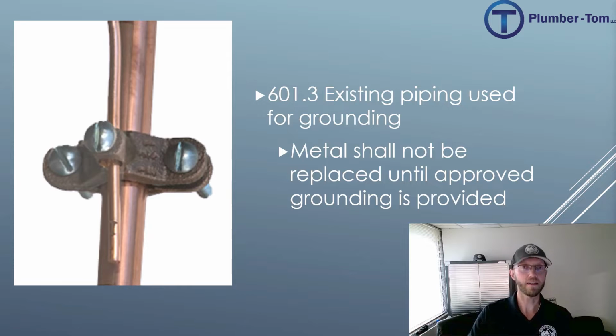But in more recent years, we have gone to plastic pipes, which means there's not a lot of conductivity in that pipe material for electricity. So let's say we're replacing a water service pipe coming into a building, and we remove the metal and we remove the ground, and we go and connect a blue plastic poly pipe right up to the underside of that, and we have then lost that ground connection.